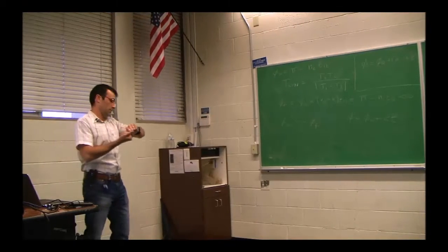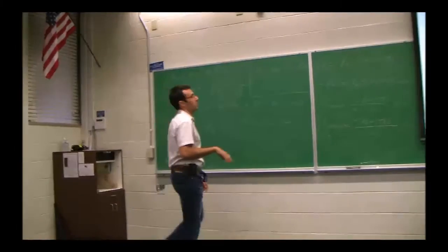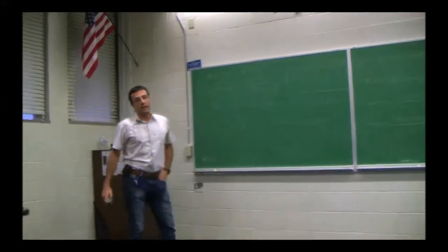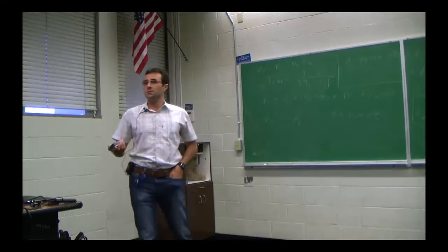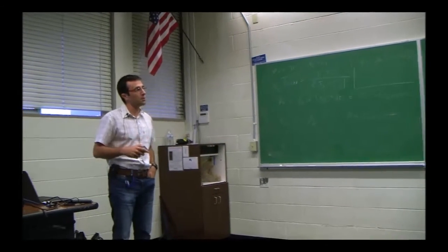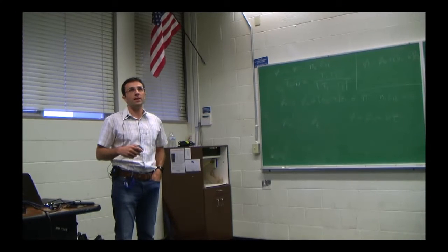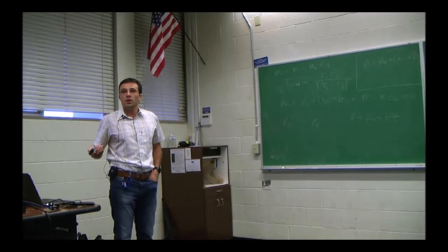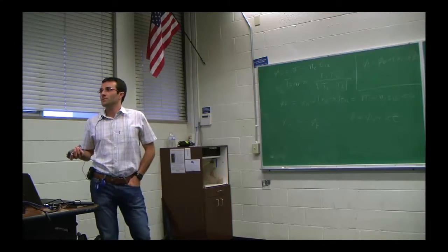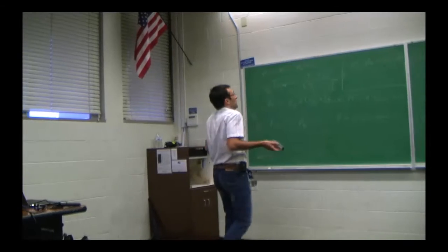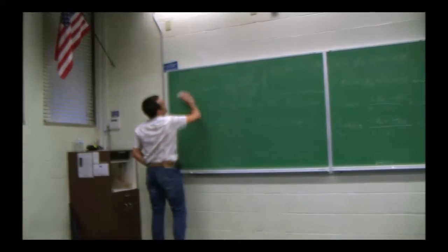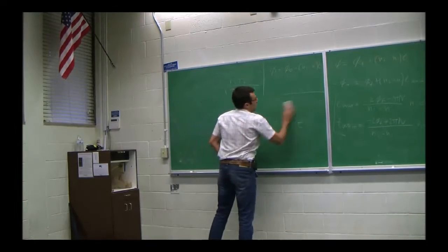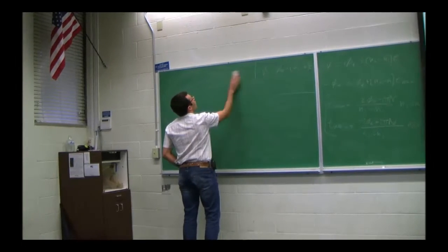because, well, if we have time, we're going to see a delta V example just to leave the planet, how much fuel it costs you. With an engine that has a specific impulse of 300 seconds, in one of the examples that your book gives you, you spend 70% of the mass of your spacecraft. So you may not have enough to even come back. So these maneuvers are extremely expensive. You need engines that are powerful enough, but at the same time very efficient, and usually the two things don't go together, as we all know. Or smarter maneuvers, or longer maneuvers.